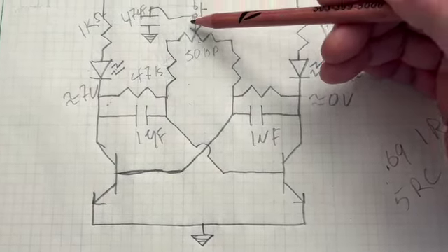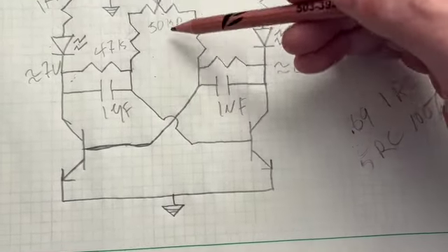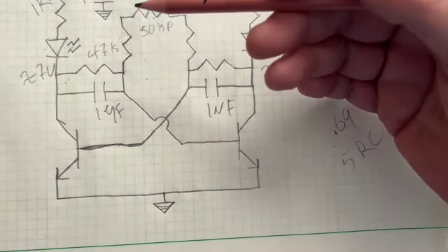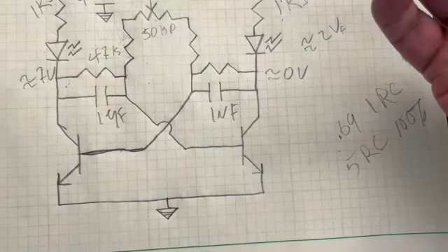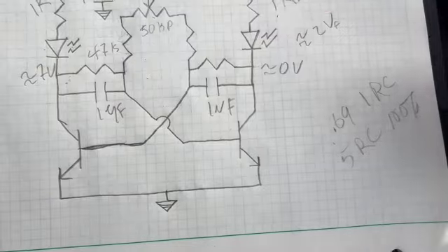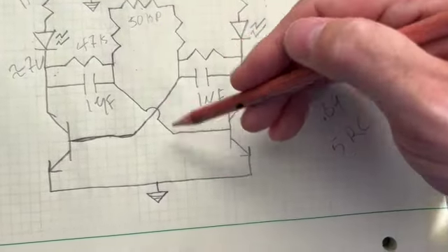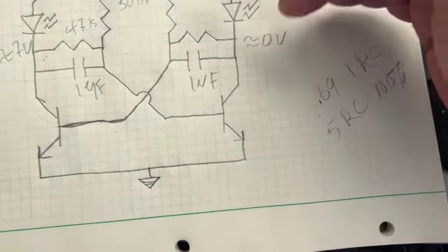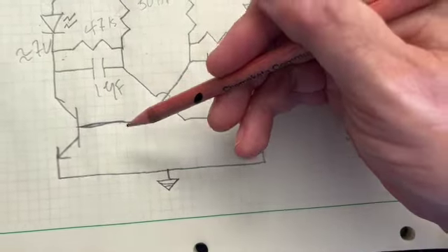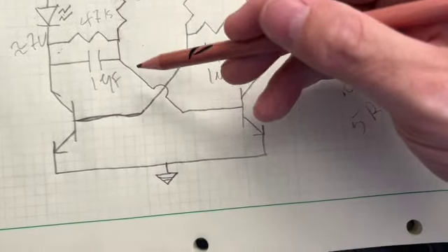You press the button, you get the 9 volts coming through here and through here, making what we got there like, let's see, 50, 75K. 9 volts across 75K. That's pretty decent current. Activates the LED, charges the capacitor.